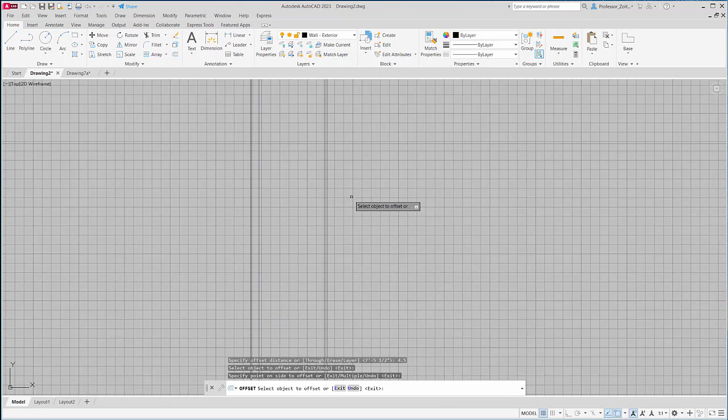The width of the water closet is how wide? Well, at the top of the screen it shows it's 3 feet wide. So offset. Here I can either type in 3 feet or the inch equivalence, which is 36 inches. Well, it says 3 feet. It's easier to type in exactly what's put down rather than try to do a conversion. So 3 plus that apostrophe beside the enter key, and press enter. And select the inner part of that wall and the inside. And then that wall again is 4.5 inches. So I'll click on offset 4.5 and click on the line and the side.